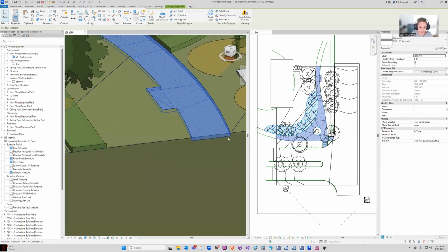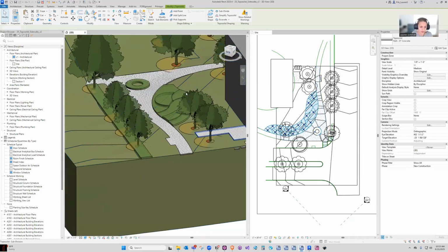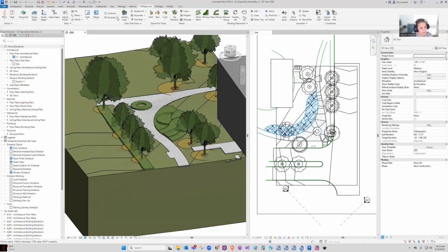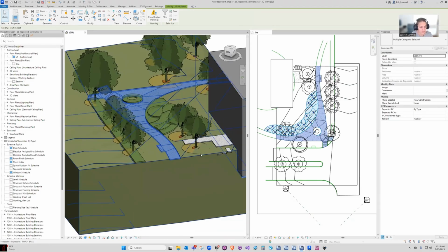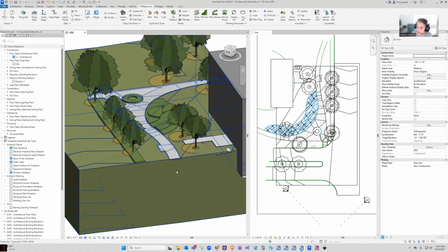So you can see this guy is excavated there, and I can actually test that as well with this foreground tool. I can find my excavations, and it's going to select them for me. I can see that that one is being excavated. So yeah, like I said, a few things to know about excavate is it does have stability issues. This is something the dev team has worked on over the past few years, and I believe in 26 they've introduced some features to try to reduce join errors. I think they still do happen in 26, but they're trying to push down the frequency that we're seeing those.